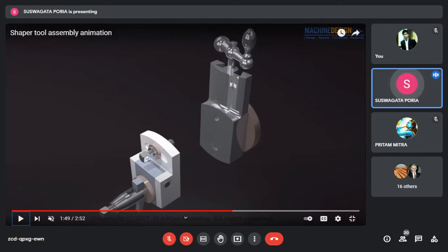Okay. So if we forget about this screw and this washer, then other than this screw and the washer, the total portion is lying under the clapper box. To fix this clapper box with this main portion, this screw and washer is required. This is the main body part. Its purpose is to transmit motion from the ram to here, and by rotating this handle, this screw will go up and down. So this total system, this total clapper box, will go up and down. So when this clapper box goes up and down, this tool also will go up and down. So by these two sub components, sub machine components, we can handle all those mechanisms. This one is the clapper box, this one is the main body part. Okay.